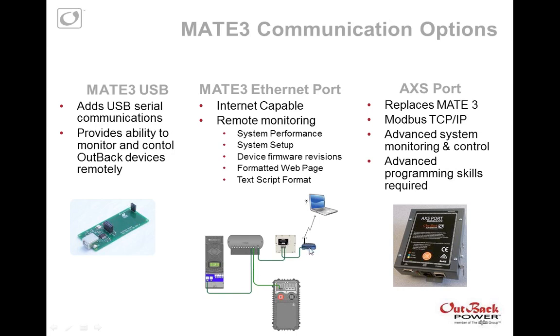Now, if you were to hook up to the internet, you'd probably run this to your main modem that comes in from the outside world, and then you would port forward this device to that main modem or router that comes from your internet service provider. Essentially, you can do remote monitoring of the system performance, setups, and device firmware revisions. You can say, gee, I wonder if they've got the latest firmware, and check that. You can get it in a formatted web page, which I'm going to show you in just a second, or in text scripts. So this is the easy way, but some people want to do more than data monitoring.